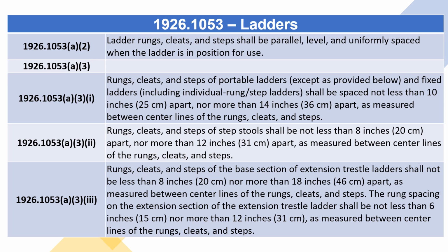1926.1053(a)(2): Ladder rungs, cleats, and steps shall be parallel, level, and uniformly spaced when the ladder is in position for use.